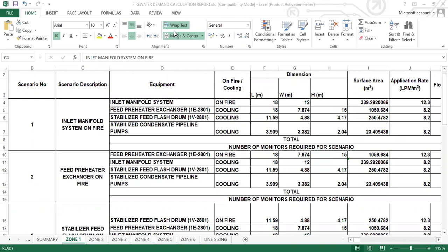So we are going to set up our system such that once your fire and gas detectors detect, depending on how we decide to do it, but typically, probably if you get up to about 20% of the lower explosive limit, your detectors will already begin to give the signal. And in some cases, by the time you're getting to 50% of your LEL, you begin to take executive action. And I think once there's a confirmed fire, whatever the philosophy is for confirmed fire for this project, the deluge valve in that area is going to be activated.